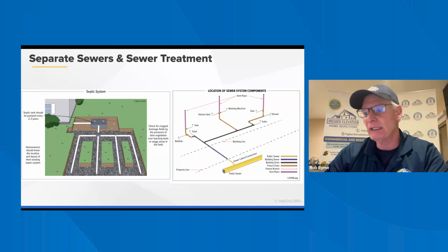Backfill should be placed in 6-inch layers, tamping it down every 6 inches. Material restrictions: make sure there are no large rocks or chunks of dirt. Not that you're going to be doing this, but it's good to understand how they do it.